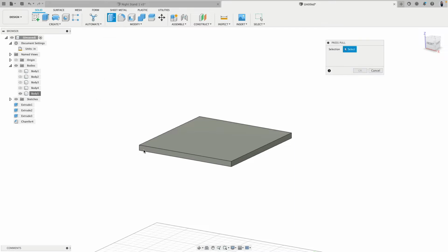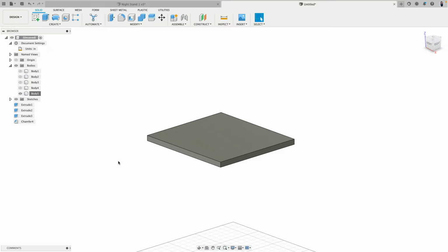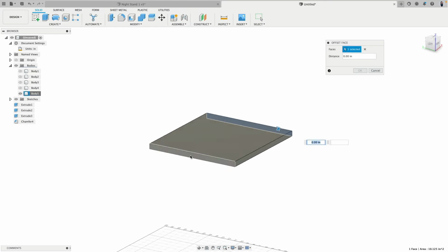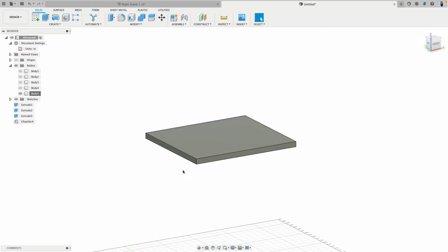Keep that in mind. So what I will do is I'm going to do the following. This piece, you see the arrow is to the left. So I have to type in now -2 inches. So I'm bringing this in by 2 inches. Then this and this, I will expand by, the sides are 3/4 of an inch. Do we bring this in 1/4 of an inch, 1/2 of an inch? Let's say 1/2 of an inch sounds better. That's nice and stable. Cool.